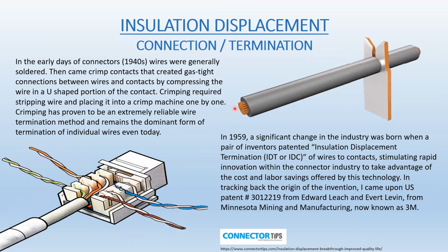What's wrong with this one here is that it's shown that the wire inside is stranded. IDC is not made for stranded cable, for stranded conductor. I kept it so I can bring your attention to it. It is made for a solid wire, because if the connector bites into the insulation to make contact, it can actually cut some of the strands. So it's not really meant for stranded wire. It's made for a solid connection.